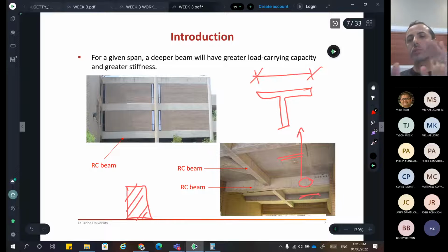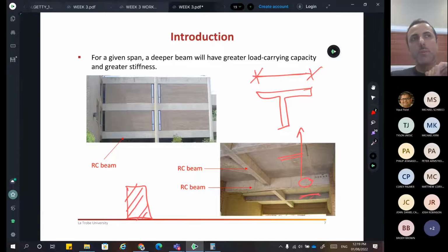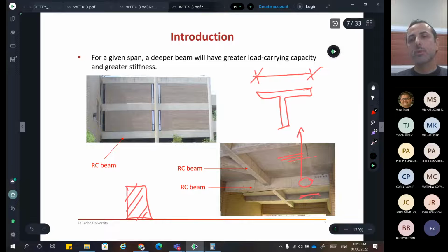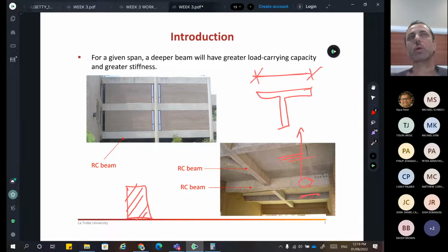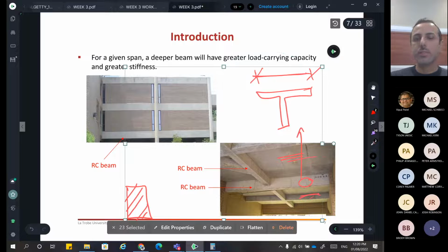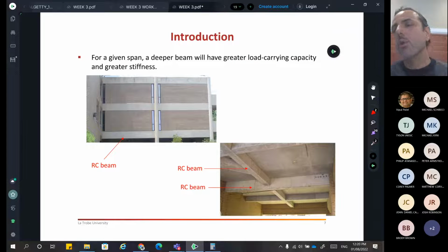No, the standards will tell you what the maximum width is. It should be about 1.5 meters or so maximum. We cannot take the full width of the slab, and we will talk about this in a special section, not this week, I think later on. However, just to let you know, our questions will not ask you to design a T section. It's not difficult. It just takes longer, and we will mention that to you when we get to that topic over the weeks.